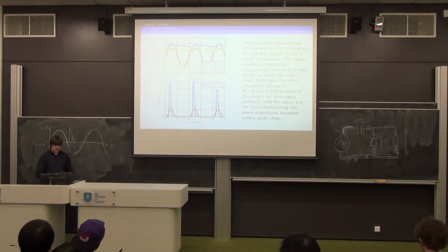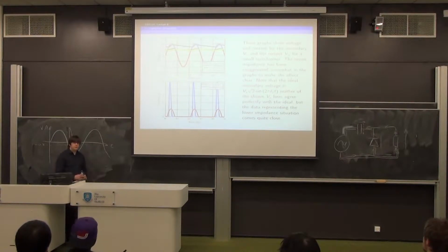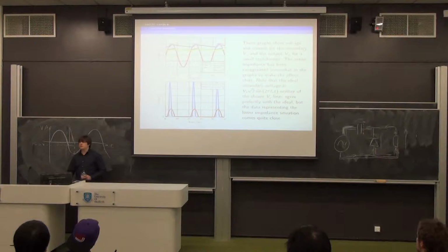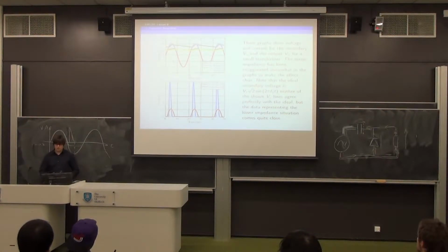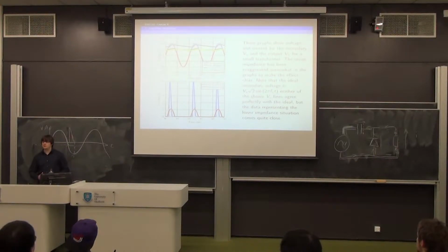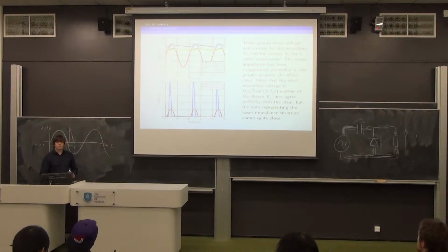Of course, ideally the green line and the black line, which are both output voltage, would be the same height, but they're not. So we lose a bit of voltage output at the expense of the transformer's inadequacies. On the other hand, those transformer inadequacies aid us in getting better current profiles in our power supply.